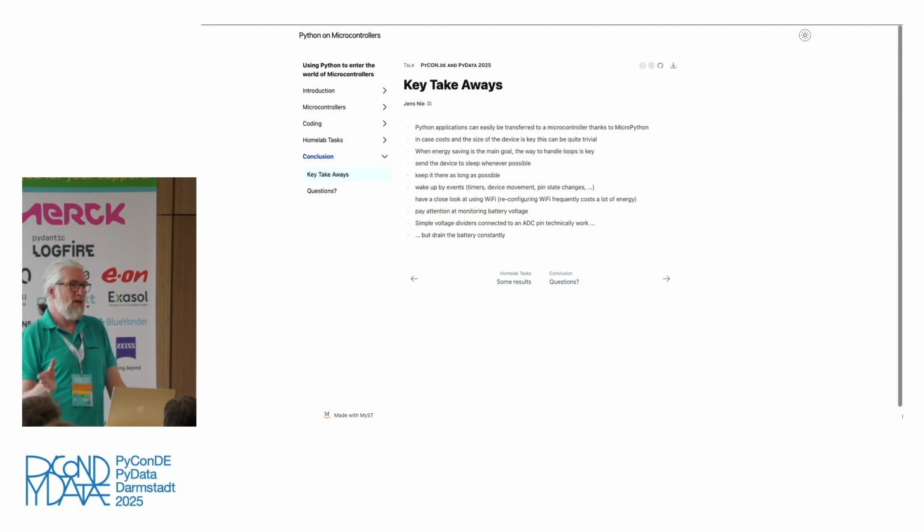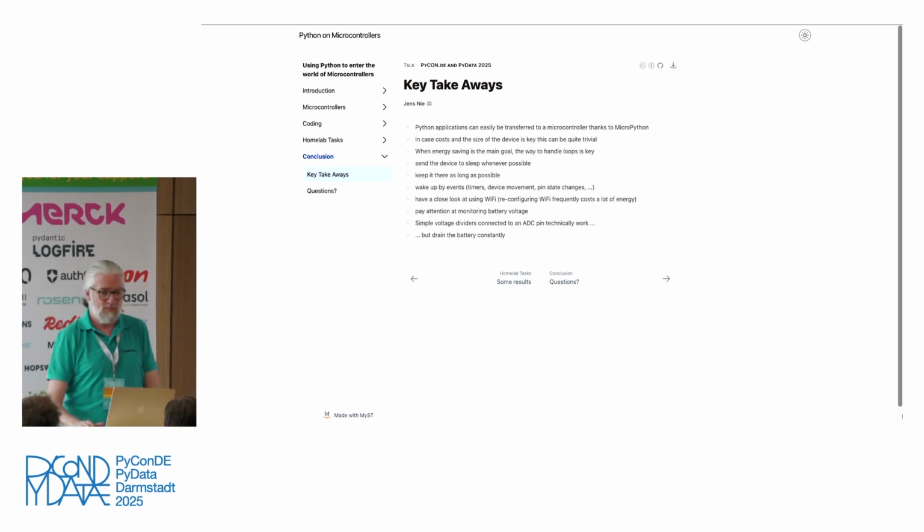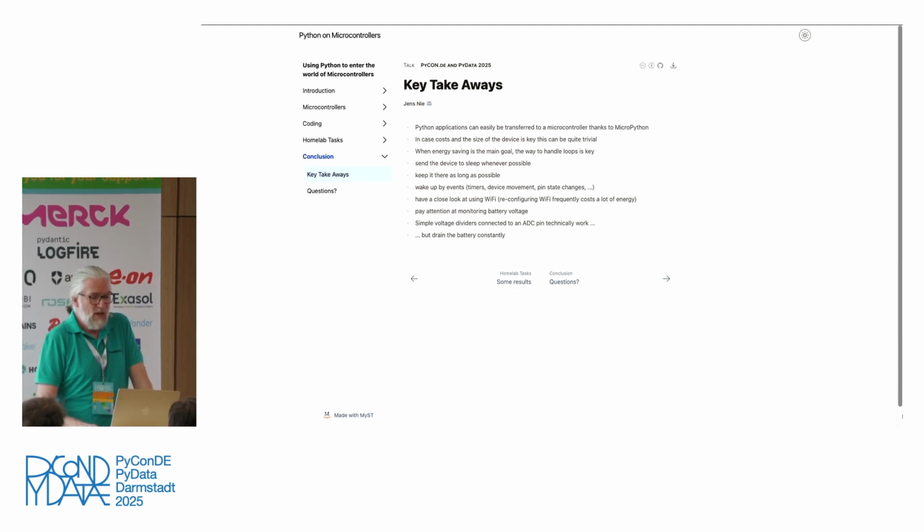And this is why devices like the ESP32 have dedicated ways to keep your Wi-Fi in some sort online while the rest is going to sleep. So it always pings after a few seconds that it's still there to keep that connection alive, and that really doesn't cost you a lot of energy, and the rest of the chip is going down in deep sleep mode. Then we are not really at microamps anymore, but it's milliamps.